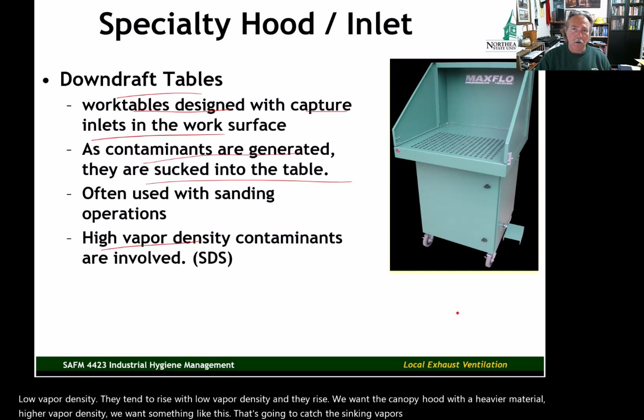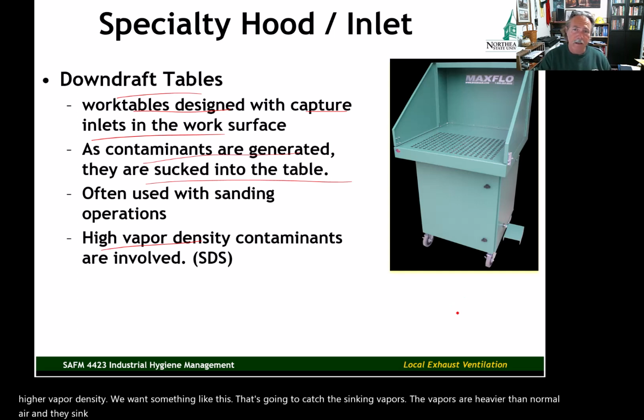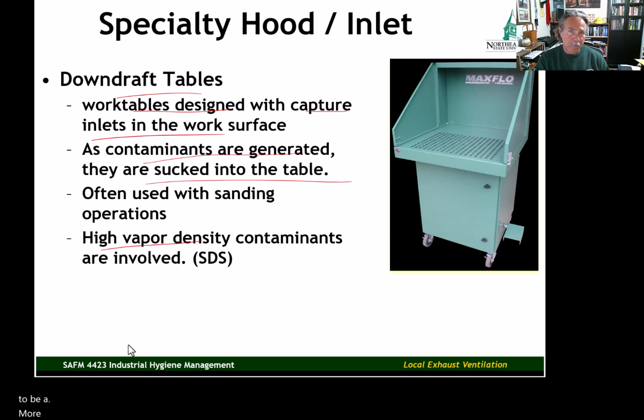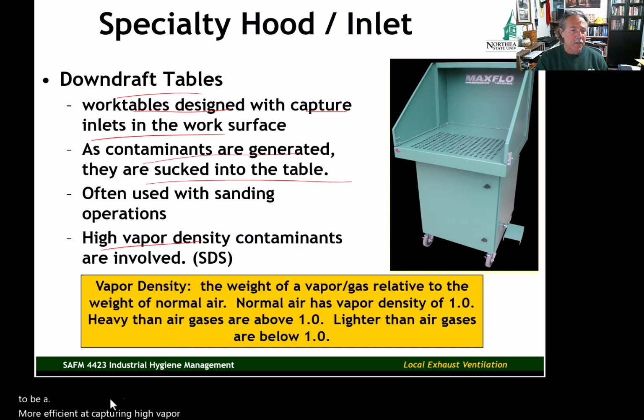The vapors are heavier than normal air and they sink as low as they can. Contain them on a table like this with the inlets in the surface of the table. That's going to be more efficient at capturing high vapor density contaminants.